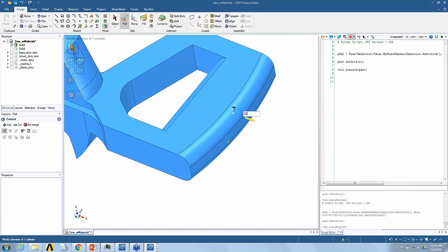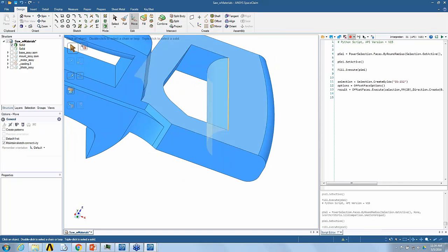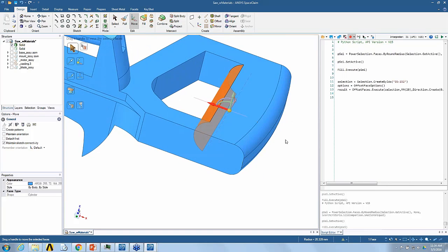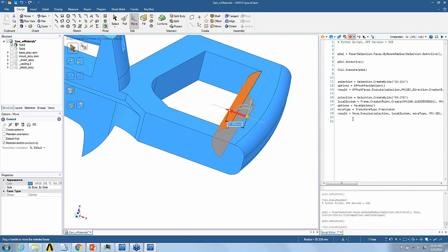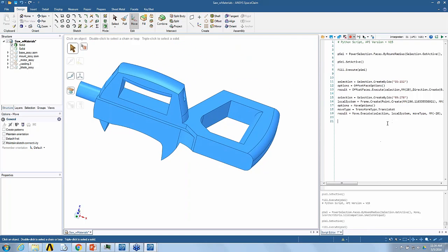And maybe we'll extrude it out by 20 millimeters. And now to make this handle stay the same width but just get longer, I'm going to use a different tool. I'm going to use the move tool. In this case, I'm going to go negative 20 millimeters too. So here I did 2 types of geometry edits. In this case, hold on, instead of typing that, let's just drag this in and type in a value. You'll notice both of these things that I did got recorded to my scripting panel, which is pretty cool.